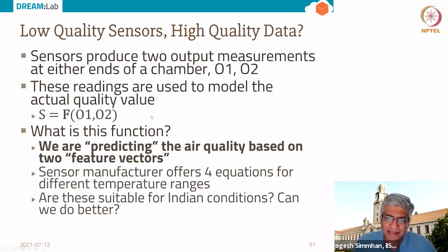But internally, what the sensor actually measures is a physical property, which in our case is the outputs from the two electrodes, O1 and O2. And internally, the sensor manufacturer has a function, called a calibration function, that goes from the values of these electrodes, which might be expressed in millivolts or something like that, and converts them into a density of a gas or particle, expressed in, let's say, parts per billion, right?